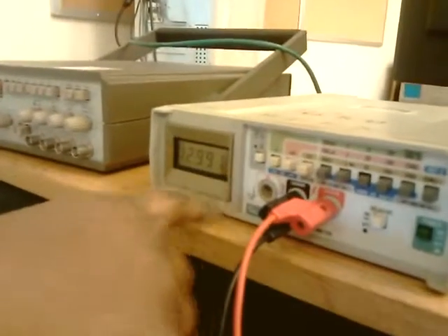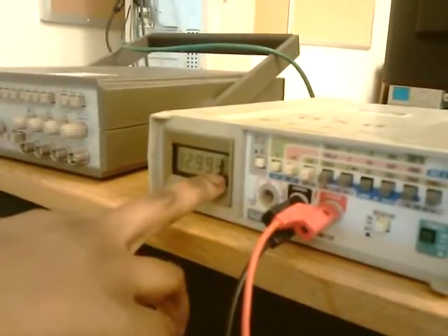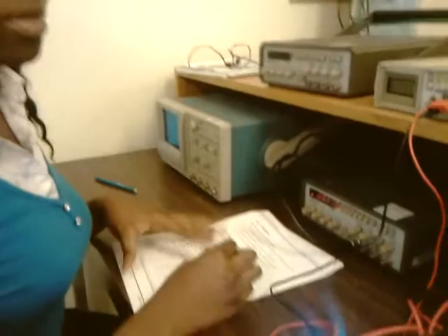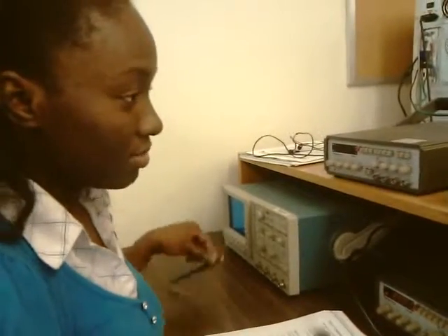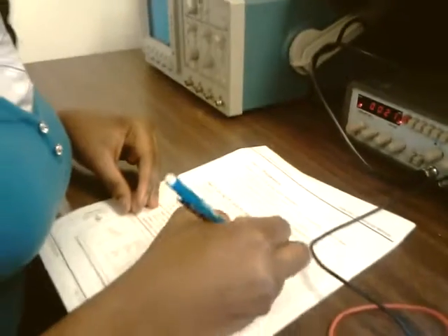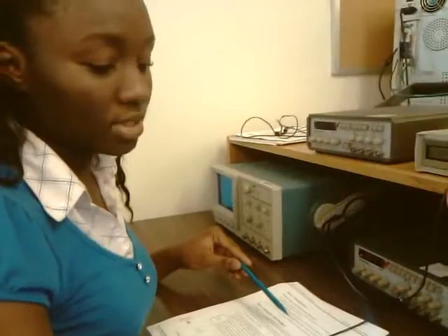And turn this on. From here, that is the multimeter. You can see the voltage here. This voltage is the cumulative voltage from both the positive and negative terminals. So to get the RMS voltage, you divide this by 2. That will be 13 volts divided by 2, which gives us 6.5 volts. So that will be our RMS voltage. We are going to use the RMS voltage to set up this circuit, to calculate the resistance of the resistor, so that the LED light will not be blown up.